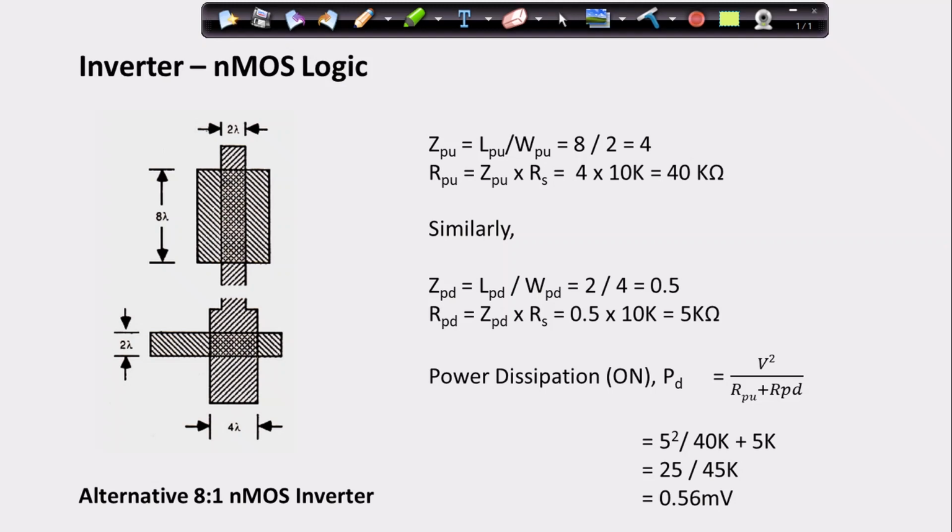By changing the areas, if I want very little area, then the power dissipation will increase. What we can tell is that if we want a low power consumption device, then the area required is going to increase. But if we don't need a low power dissipation device and I want very little area, then I can go for these similar types of logics, but the power dissipation will be more.